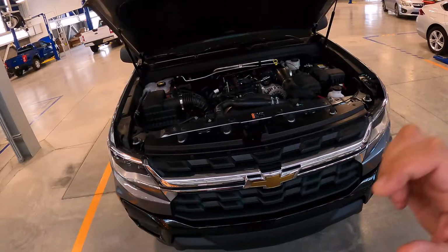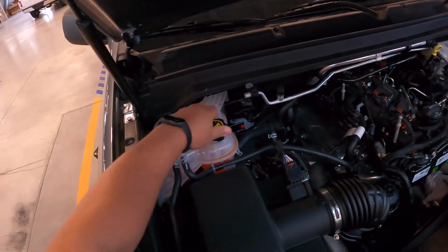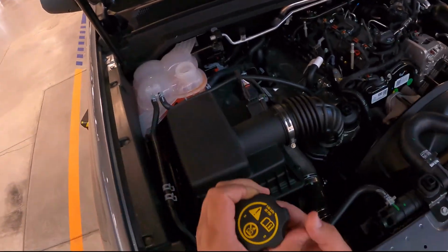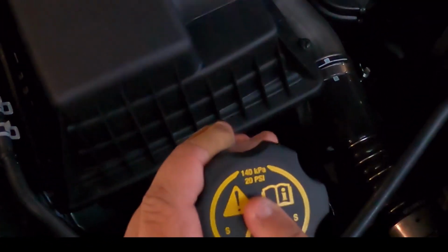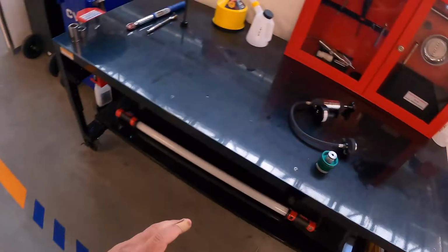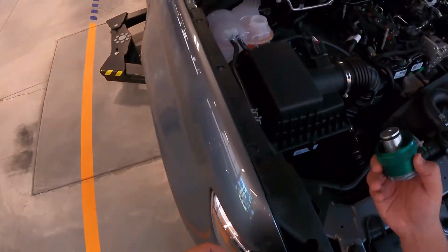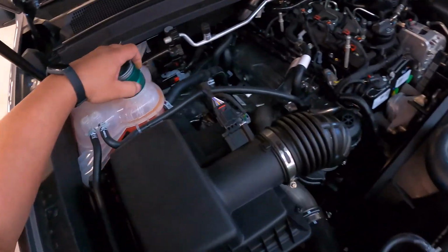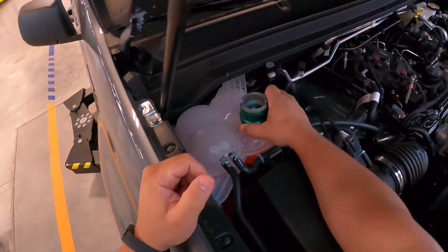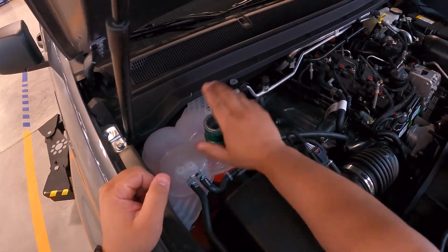So here we go. We're going to start by removing the coolant pressure cap. So go ahead and unscrew that and take a close look at that cap where it says 20 psi, which is what the system pressure is and what we're going to pressurize it to. So with the cap out of the way, you're going to put your adapter on. Just screws on tight. Make sure it goes on by hand, no tools. Tighten it till it seats all the way down so the gasket is set.